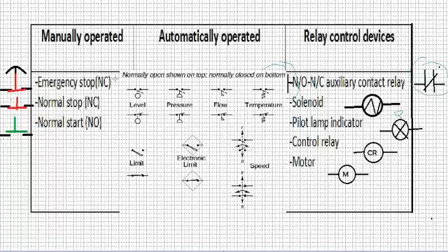So these are all the various symbols that can be utilized to represent different kinds of contacts in different electrical schematics. This is going to make more sense to you as we dig in deeper into this idea of relay schematic and how it's tied to ladder logic, because in reality you will have great opportunities if you're a plant engineer, plant personnel, maintenance personnel, to do what they call retrofitting. And retrofitting is basically taking a conventionally controlled machine, electromechanical machine, and adding on an automatic control to the machine.